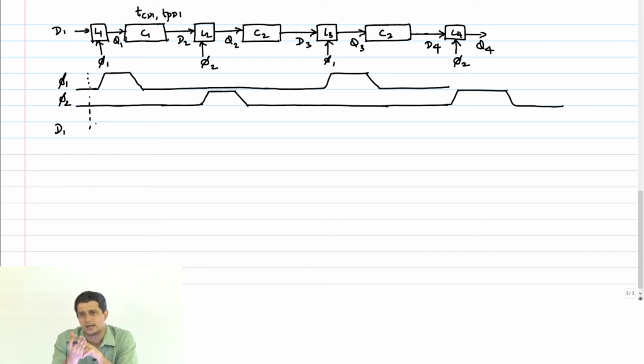It can change inside, and that is really the worst case, because I eat up some time and I still have to achieve this state, right? If you make the data change before the rising edge, then you have a lot more time to finish your thing.